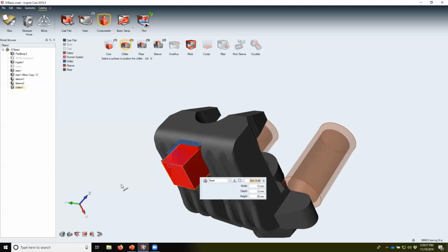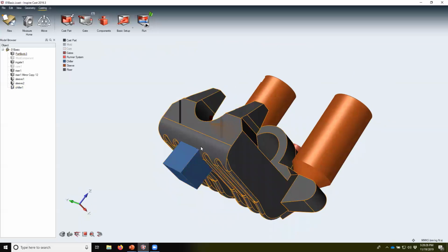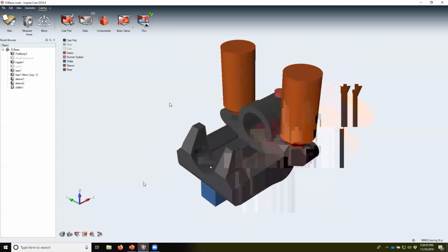And you can see too, with the way these one-click components work, it overlaps that geometry. If you've run any structural analysis in SolidWorks Simulation, for example, you know that it doesn't like overlapping geometry. But in this tool, the way it handles overlapping geometries is it automatically does some combine features, some Boolean operations. It'll automatically subtract one body from another. It prefers the casting body. That's the high priority. It'll subtract from other bodies to get the right size and shape of these. So it automatically does a lot of that Boolean work in the background.